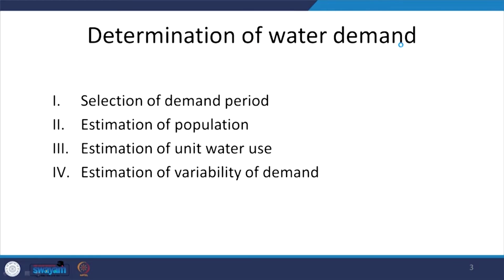That's something that we need to be able to look at. So why do I need to do that? Obviously, I need to know how much capacity my plant should be able to cater to. For example, I can look at the need right now and build a plant, but the plant construction itself might take 2 years, and then the population might increase, might decrease, but rarely, at least stagnant or increase, and then I will be left with a redundant plant pretty soon, in 5 years.